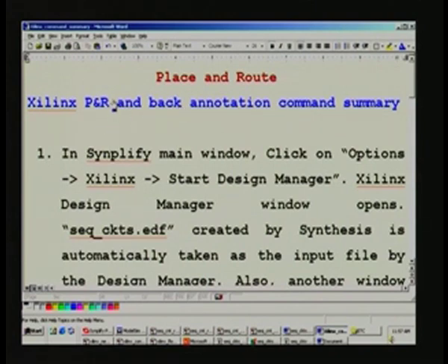The next step after place and route is what is called back annotation. Only here the actual gate delays etc. will come into the picture, and subsequent to this you have to take the back annotated file, which is also a .v file, into the ModelSim simulator and run the simulation once again, and satisfy yourselves regarding the functionality, and therein you will get actual gate delays reflected.